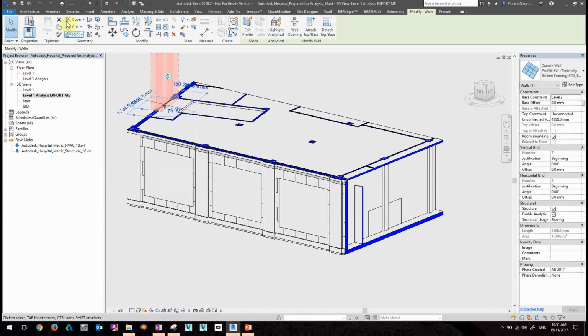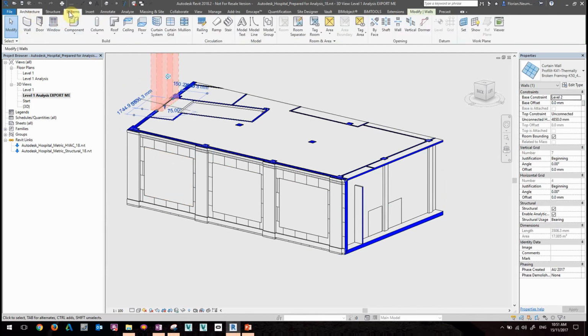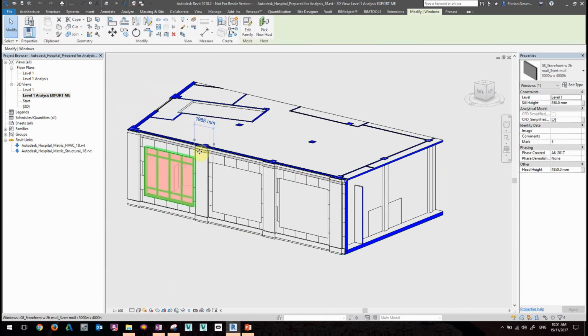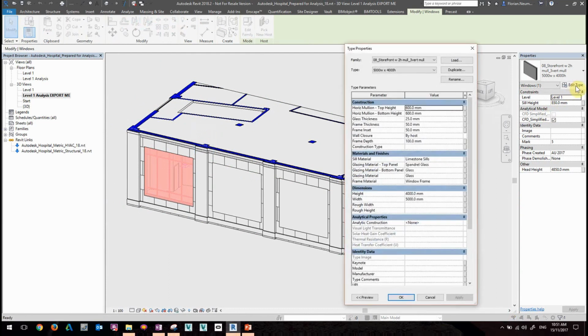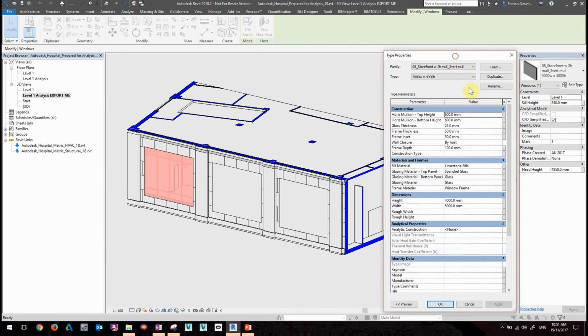If I want to model something, I select one of my tools for that. Good. And then I have my instance parameter as well as my type parameter, and I inspect these. I have 5 areas to inspect in Revit. This is my contextual tab I'm pointing at right now, my options bar, my properties, my type properties, and my symbols. So these are the 5 areas we have to inspect. There's nothing more out in Revit. Revit has a contextual user interface.